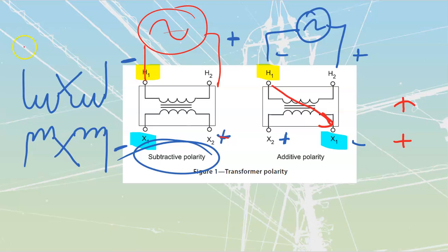And then I'm just going to designate these ones. Once again, if this is my high voltage side, I'm going to look at the upper left corner, and I'm going to label that one H1. H1 will always terminate onto an H2. So this here would become an H2, and then I would loop to here. This is going to become an H3. Really, this is the H2. We just draw them crossed over like this. Later on, you'll see why that's convenient to draw them like that. And then this would be my H4.